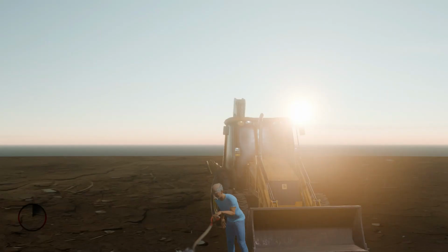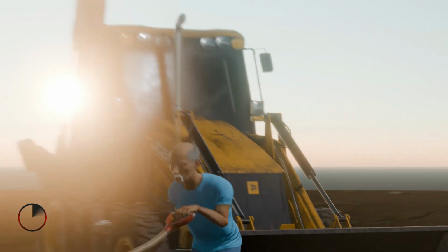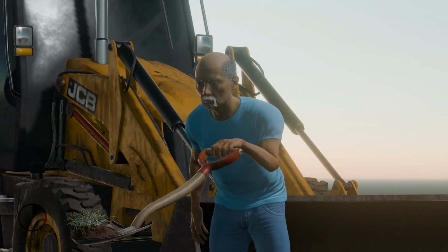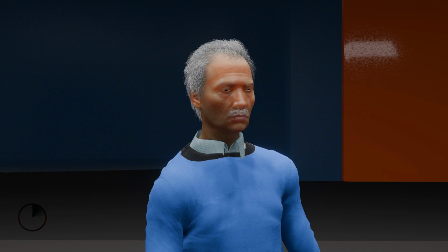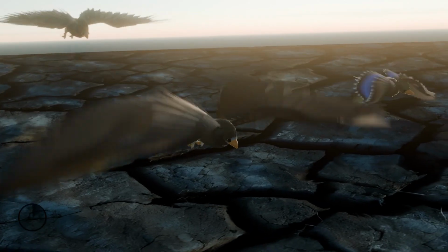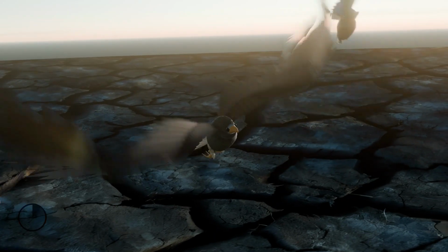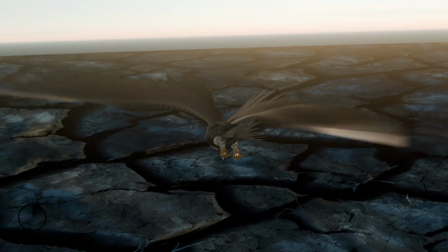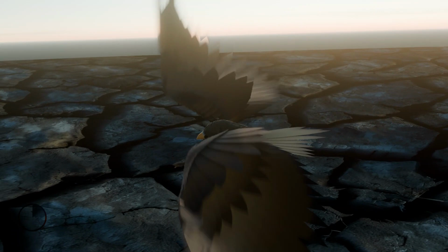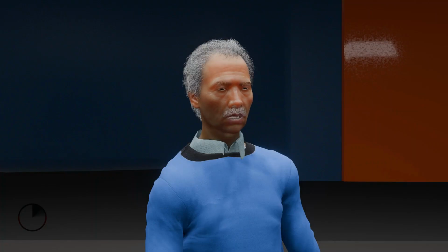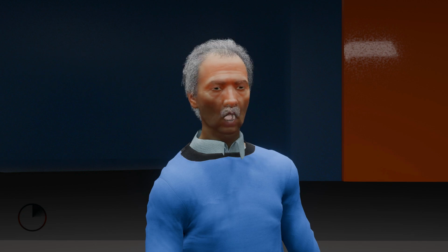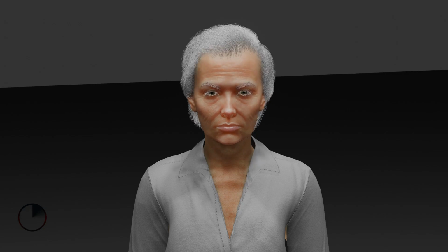In this case, the soil and rock condition is checked, and in a case where the soil appears to be weak or the rock appears to be weathered, the weak spot is cleared, thereby allowing the dam construction to be laid on a solid foundation. After construction, the temporary diversion will be removed, thereby allowing the water to be collected and stored before it will be channeled to the turbine via the penstock. Let's look at it in terms of water discharge to and fro from the dam.